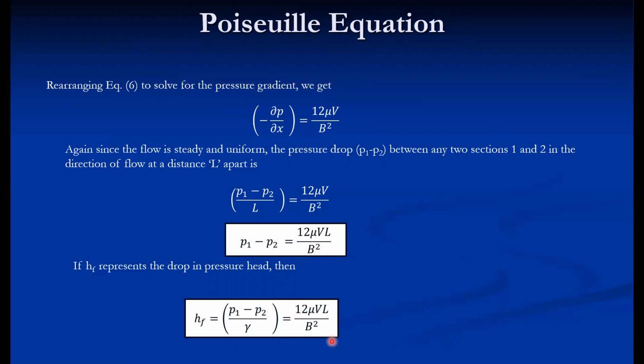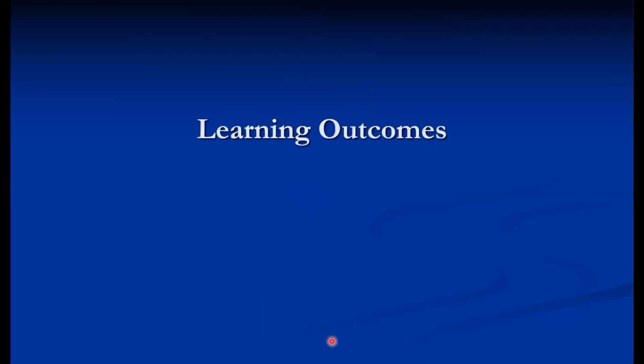These expressions are only applicable when laminar flow takes place between any narrow passage, or between two fixed plates. In case of leakages, sometimes we consider two surfaces, and in between the two surfaces a leakage takes place. In order to calculate that leakage also, we consider the two surfaces as parallel fixed plates. So many practical situations we convert into this particular situation, that is fixed parallel plates. So in order to calculate the pressure drop and the discharge, velocity becomes useful. So that's it from this particular session.